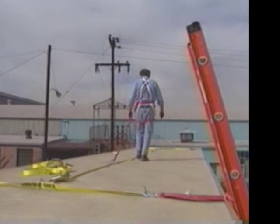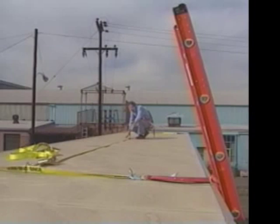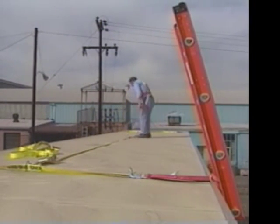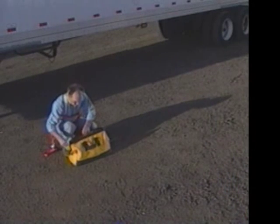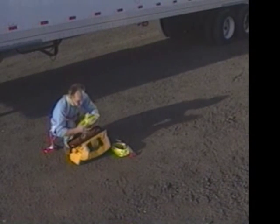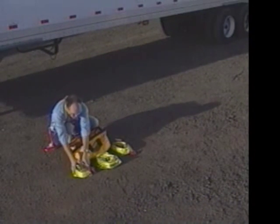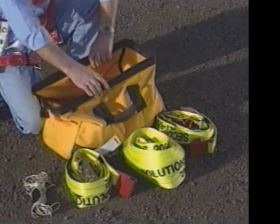Once you have been outfitted with a personal fall arrest system, you must also use a fall protection system designed for your work situation. When working on the roof of a semi-truck trailer, use this strap and harness assembly. The assembly provides anchorage points on the top of the semi-trailer. It consists of two 30-foot cross straps with ratchets, fixed D-rings, buffer pads, and flat hooks. Also included is a 50-foot center strap with ratchets, locking safety snaps, and a sliding D-ring. A throw line that is weighted at one end is also provided.